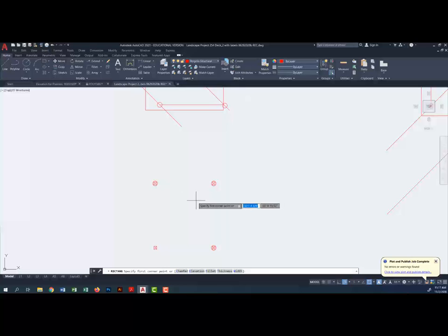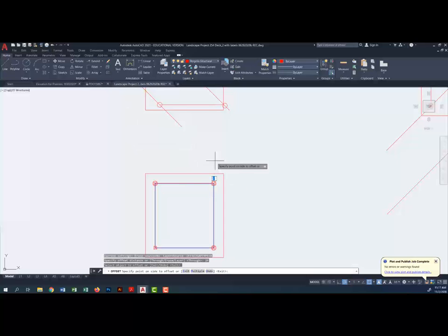And I'll use the rectangle command, and I'll go right from the center of the post to the center of the post. And because I've rotated, it's now a perfect rectangle. And I'm going to offset that 2 feet, so 24 inches. There is the outer edges of all my joists that I'm going to have, both the ceiling joists and the 2 lintels. Okay, let's remove that.